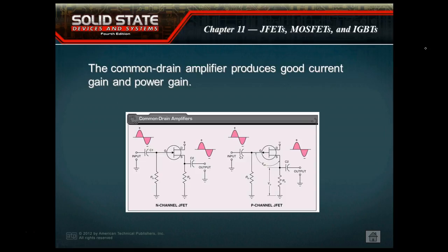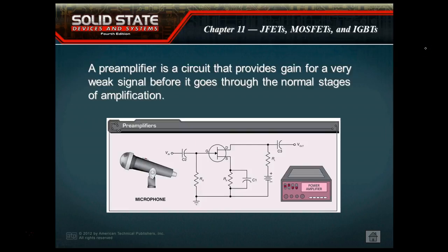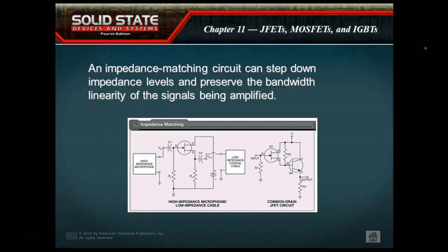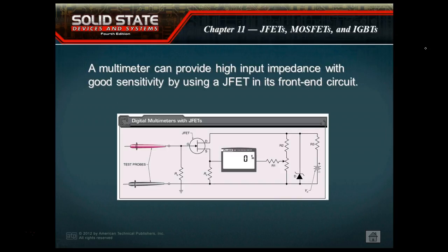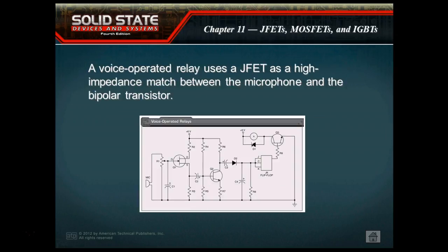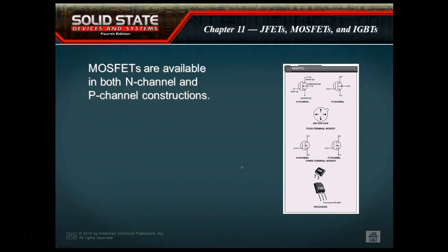So you got to be real careful when we talk about common, because that's common to the circuit, but we're talking about the common to the AC signal, not the DC. We looked at using a common source to amplify a microphone. We looked at a common drain. We looked at a common source that would be used for meter testing. And this is a common drain, used to drive the base of a bipolar transistor.